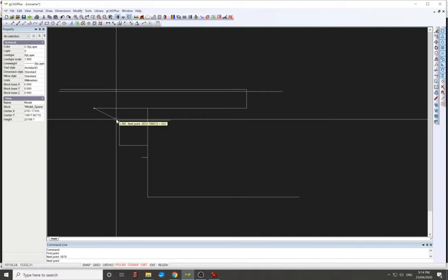If you're doing a new house that hasn't been built yet, you might be asked to do it off a plan, which is easy to do. I might do another video about that. But I still don't trust the measurements and final positioning of everything in the boundary, so I would rather go out, do a drawing around the house, measure everything and just get it spot on and be sure. Sometimes you don't get a choice because obviously it hasn't been built yet, but I will show you one I'm doing at the moment